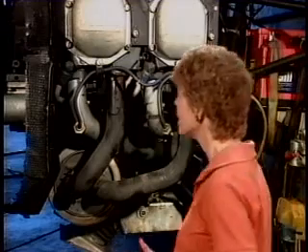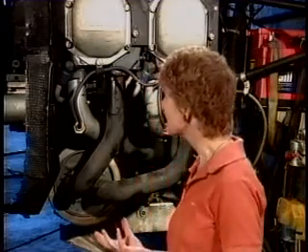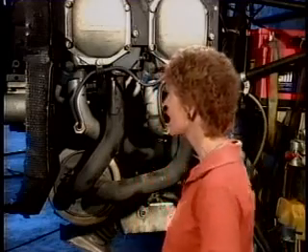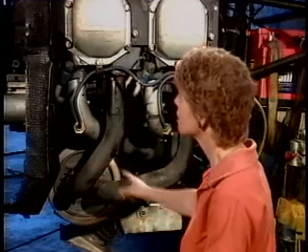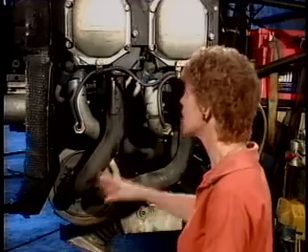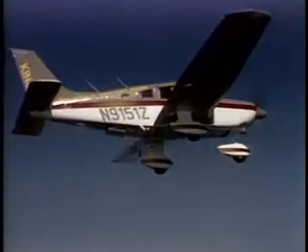Now, smaller general aviation aircraft use basically a heat exchanger or a jacket around the engine exhaust as the heat source for heat for the cabin. And when you're inspecting the heating and exhaust systems on those kind of aircraft, you not only want to look at it very closely physically, but you also want to periodically do an operational carbon monoxide detection test. And the reason for that is, with the heat exchanger setup, if you get a leak in that, carbon monoxide can end up leaking into the aircraft cabin. And if you're in flight, the last thing you want is carbon monoxide in the cabin.